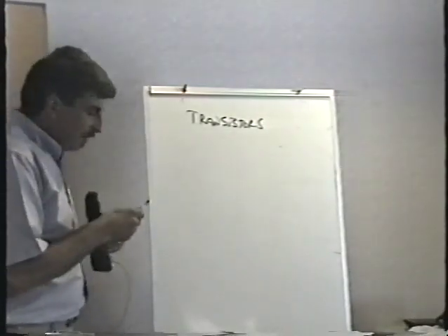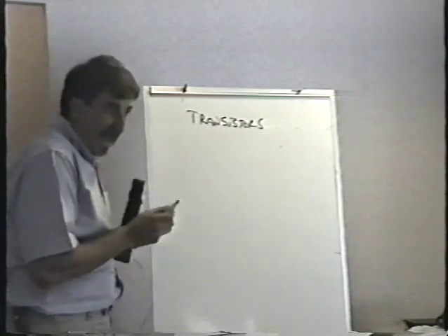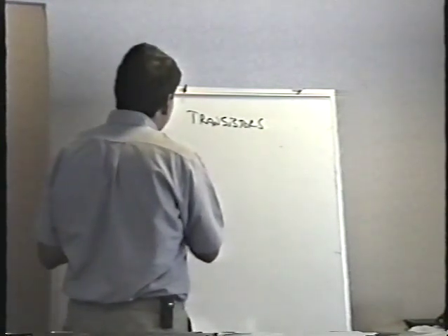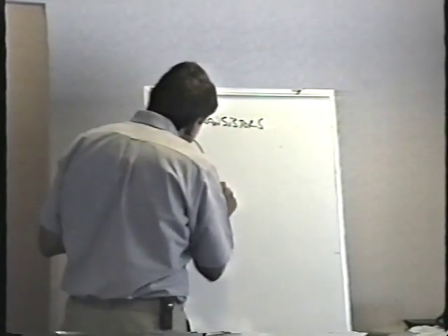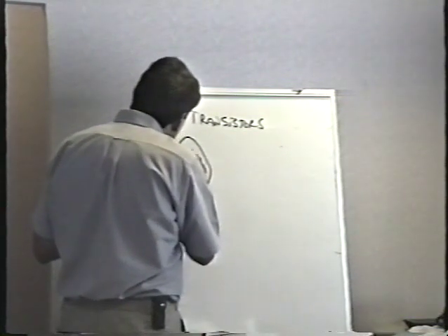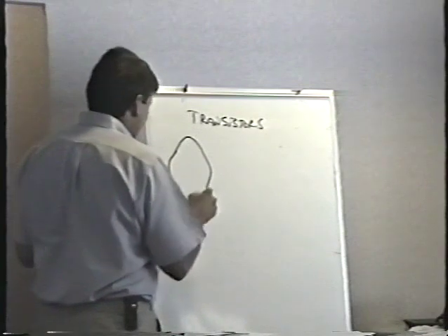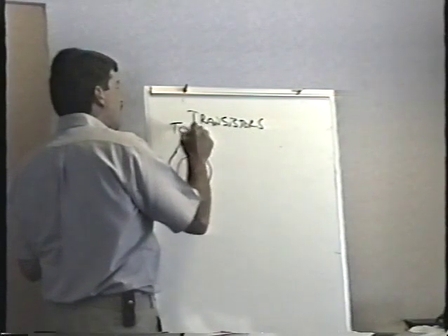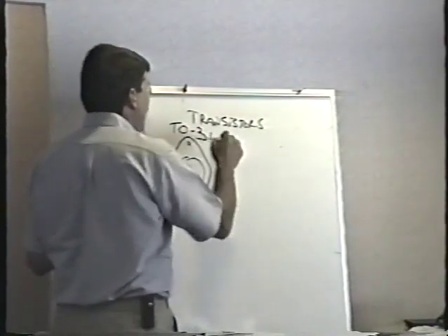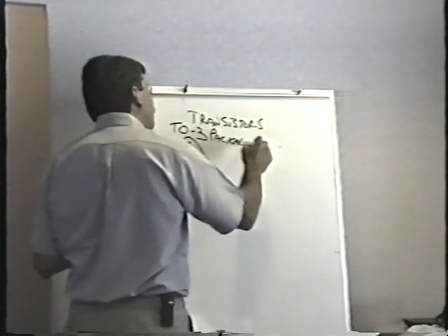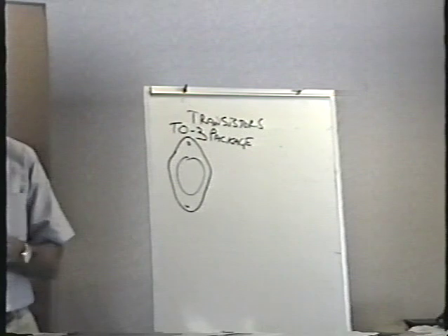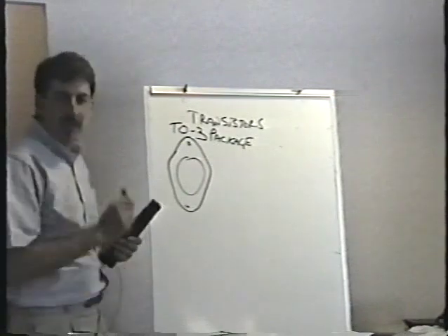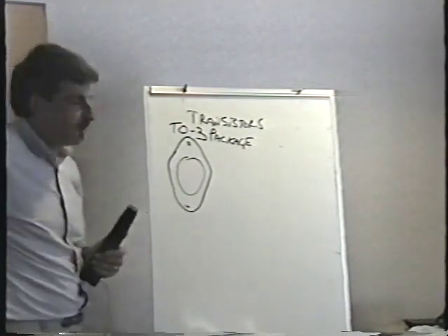Transistors come in a wide variety of different shapes and sizes, different packages. You have 3 of those different packages, and each package has a different designation. The giant transistor that I gave you that looks kind of like that, not exactly, this kind of guy right here, is known as a transistor in the TO3 package. That's transistor outline number 3, which is really where that came from. Commonly referred to as a power transistor, but it's really just a transistor in the TO3 package.